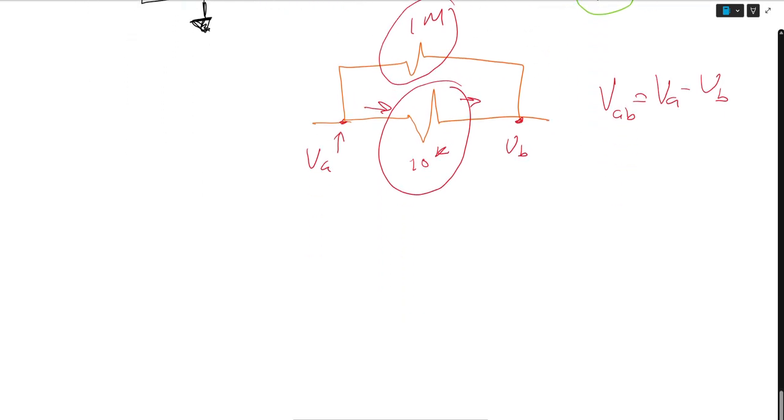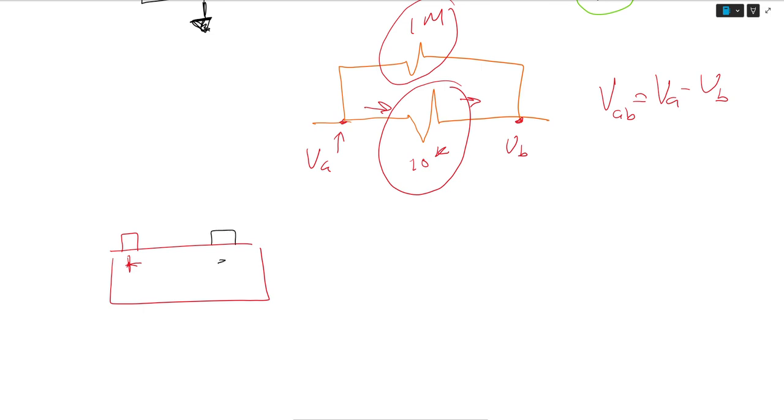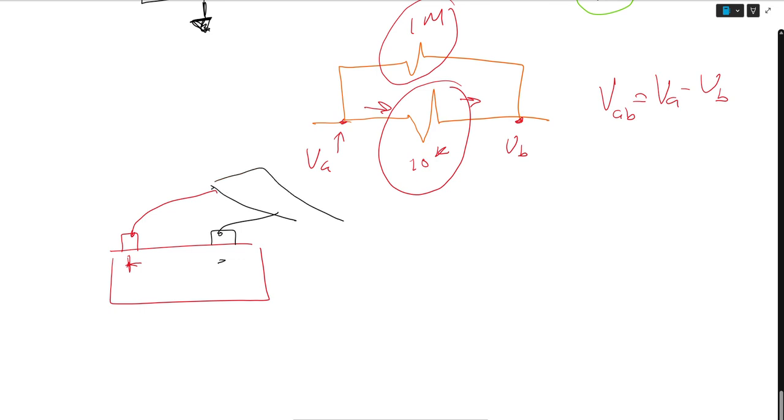A real life example of this is if you have your battery in your car. It looks something like this. There's a plus sticking out. There's the minus. You can take a voltmeter, which you can buy online for like $10, and put the red lead here, and you could put the black lead here and measure your voltage, and you would get the charge of your battery.